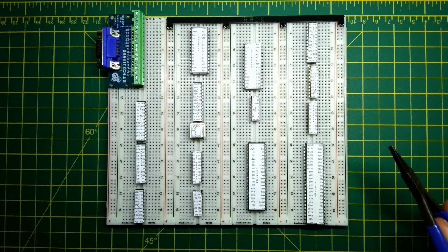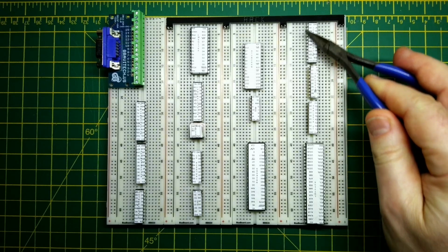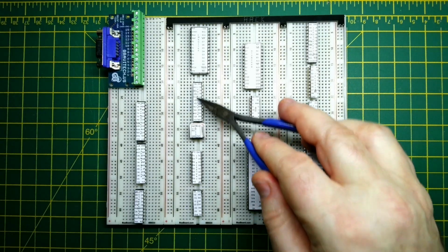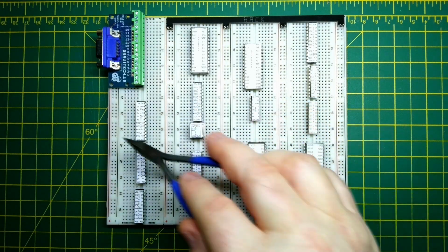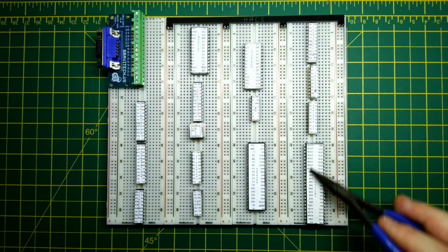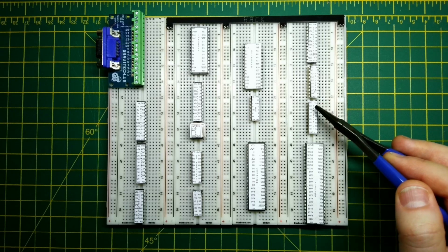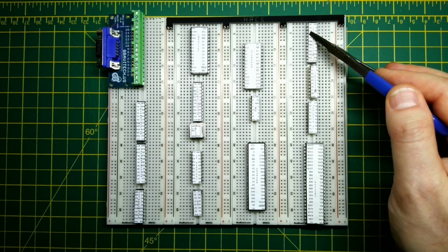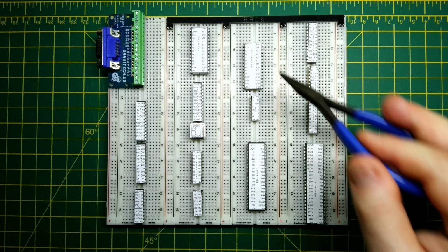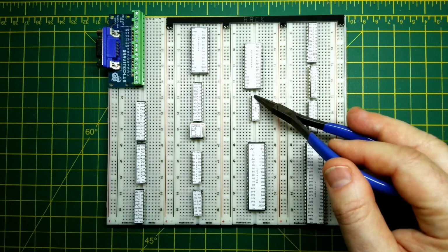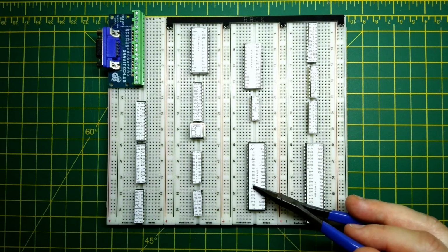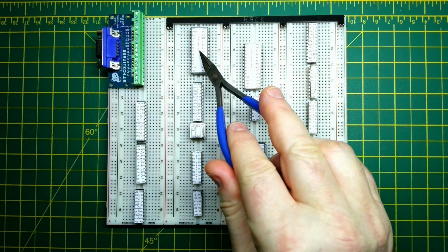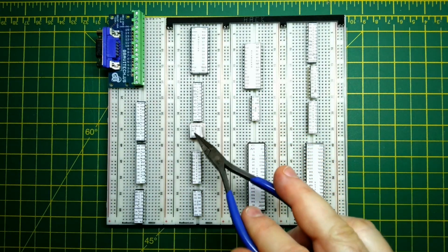The things we're actually going to be focusing on for the rest of this video are the IO decoder, the clock crystal oscillator, and the clock PLD itself. All I've done is laid out these other ones. So this was the dual port RAM, this is the character latch, this is the CRT status. As we already said, this is the IO decoder, this is the character ROM, the shift register, this is a CRTC controller, and then we've got our VGA digital analog converter, and the clock, as we said, the oscillator.